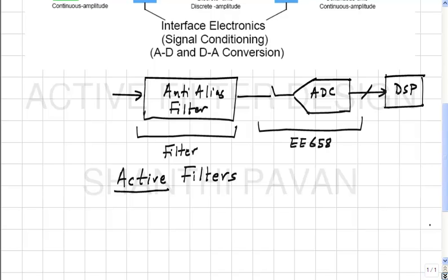Now, if you want to realize a millisecond time constant using only R's and C's, and you choose for example a kilo ohm, what kind of capacitance will you require? A microfarad. And you know that it's okay to build discrete circuits using a microfarad, but on an IC for example a microfarad is a complete no-no, simply because the area occupied by the capacitor will be so huge that whatever else you build will be this small, and then there's this big microfarad capacitor.